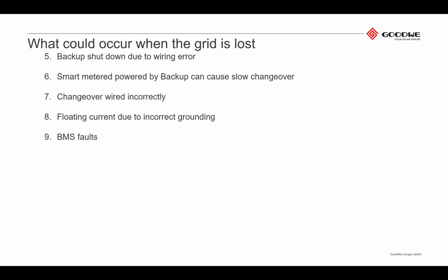So it's very important that the smart meter goes off along with the grid, so it doesn't send conflicting information to the inverter. And for the accuracy of your metering as well, it's always advisable to have your CT connection point and the voltage reading to the meter as close together as possible.